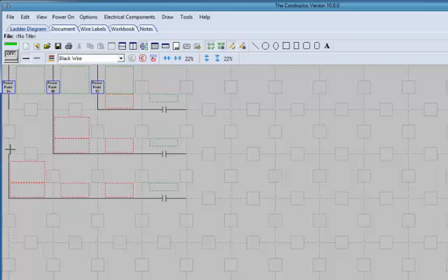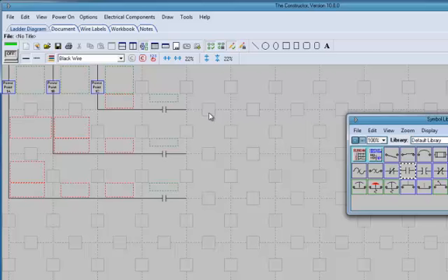What comes after that on the motor starter and on our drawing then is our overloads. However, unlike the overload symbol we have been using in the control circuit part of our drawing, this section, because it is the power section, uses the power version symbol of the overload, which, if we go to our library, we see is this one marked overload switch.